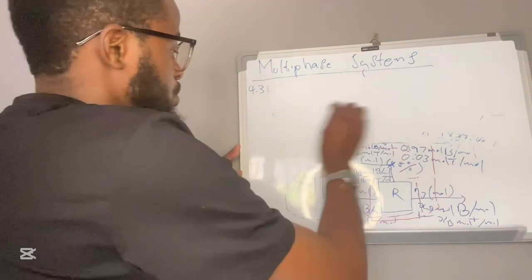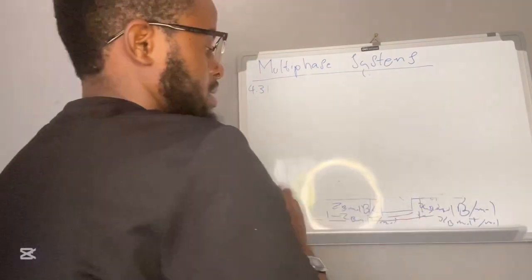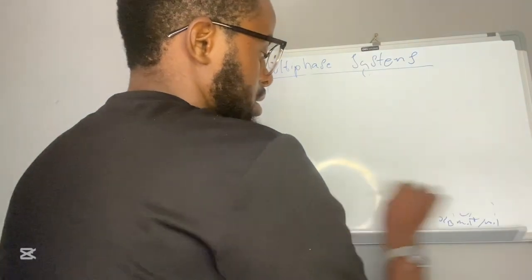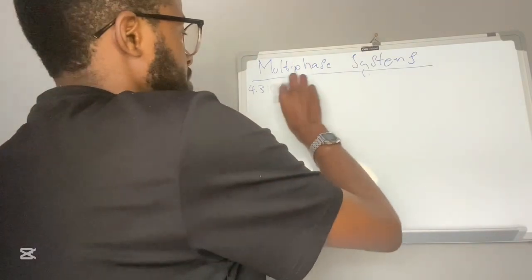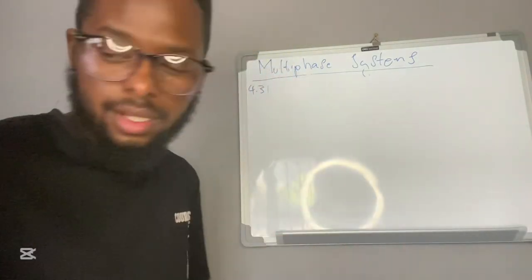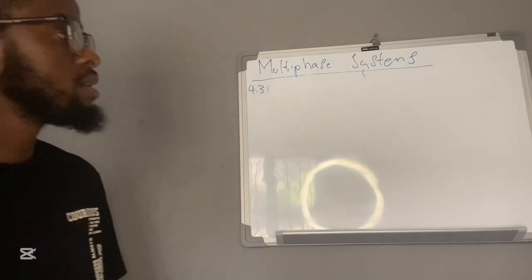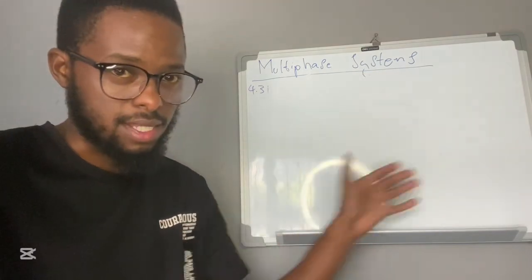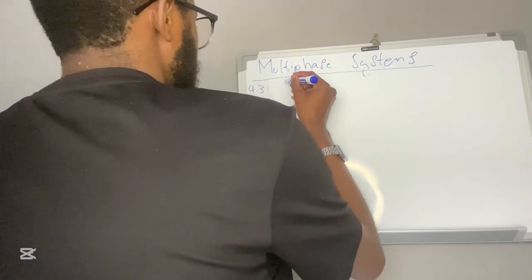So now they're saying do the flowcharts and do a degree of freedom analysis until you get one with the applicable DOF. As I've done this question, there's only one that has an applicable DOF in this case. All the other ones have greater than 0 DOFs. So this is how it's going to go. So we start with the overall. I will assume you guys have written down the flowchart, since I don't have it right here. So we'll start with the overall.